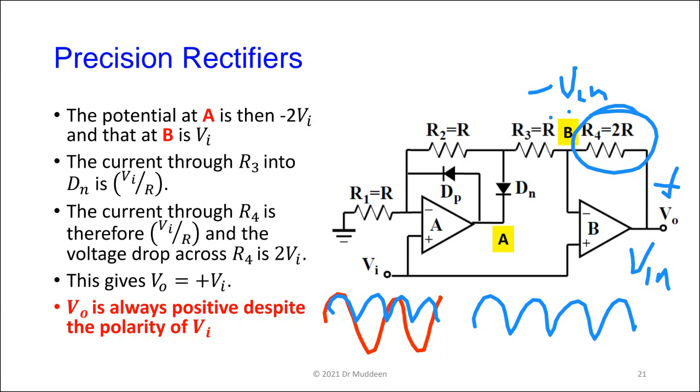That's why we say that the addition of the diodes to the op amp creates an ideal diode behavior. The diode doesn't need 0.7 volts to turn on. The instant you put in a voltage above the minimum input voltage, of course, all op amps have a minimum voltage in the small millivolt range that it must take before it responds. But as soon as you exceed that minimum voltage, the op amp turns on.